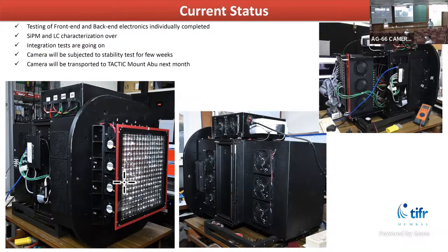Any other questions? Please use mics. So how do you implement that soft core IP in your design? Soft core processor. Yes, soft core processor. This is NIOS, proprietary of Altera. For that they have given this software Eclipse. So we run through that, and then hardware and the soft code are combined together, and the final firmware file is generated, and that we store into the flash memory of the FPGA. Okay, thank you.